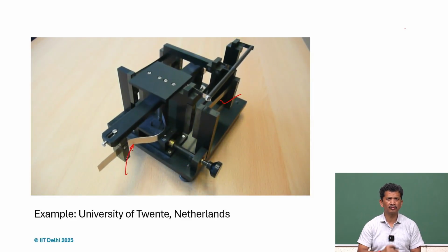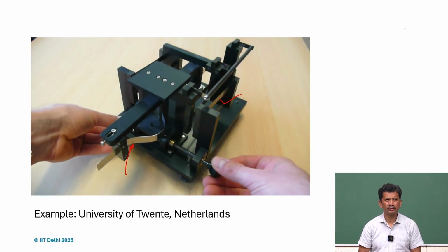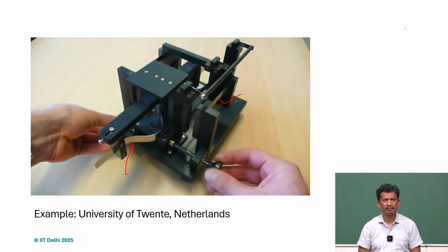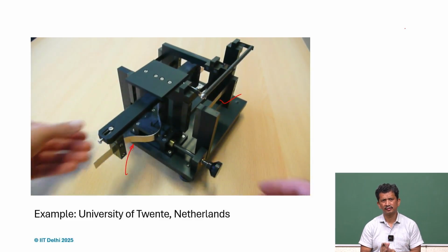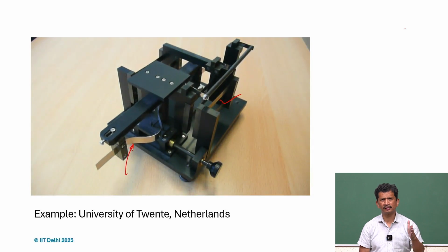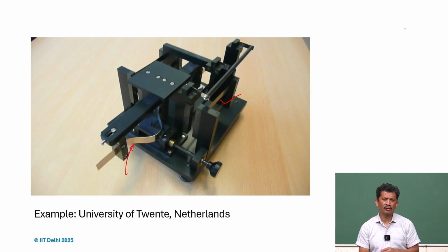By tuning, now you can see the frequency is higher, so it means k is high, but as you tune it and the positive and negative stiffness balance, you realize that the free vibration mode, the fundamental mode, is really small. If we compare with the square root of k divided by m, the k is near 0. It means that omega can be very small.